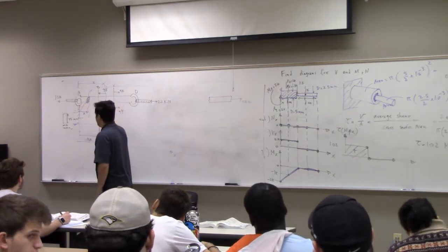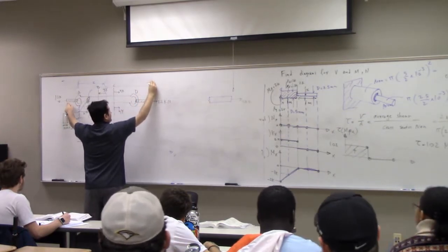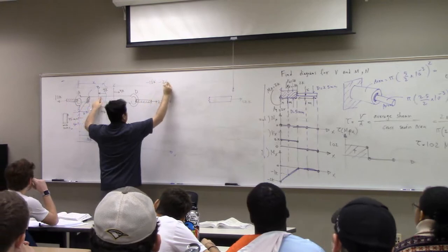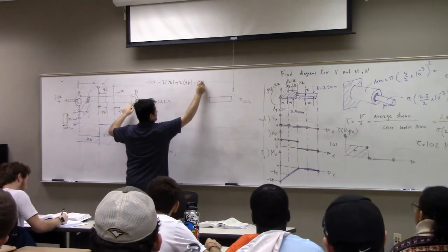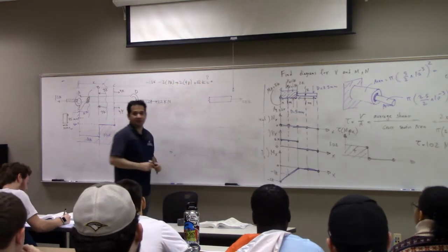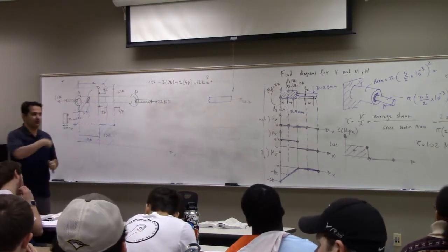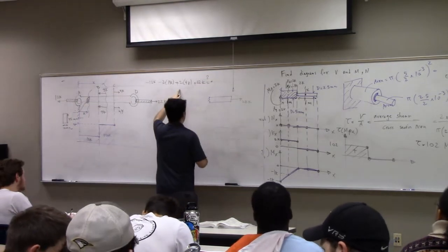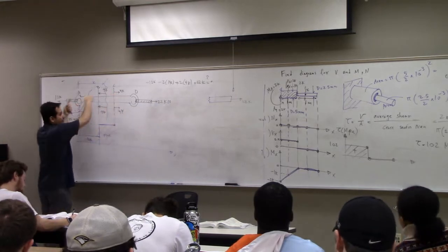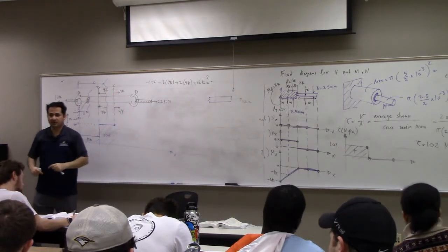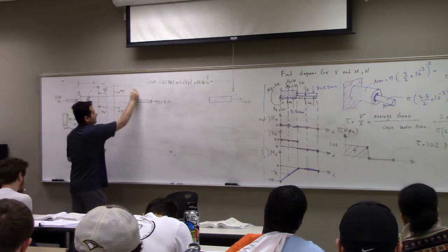So in fact, if you sum all the external loads, what do you have? You have negative 12, negative 2 times 9K plus 2 times 4K plus 22K. Does it sum to 0? The answer is yes. So that's possible. Always do some sort of investigation before you actually solve the example. So that makes sense. Now, if I draw 20K, I don't consider this 4K because the overall plot is already taken into account. You just cut it here and consider this part.